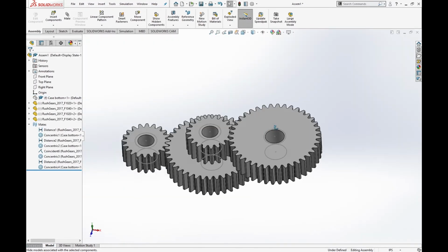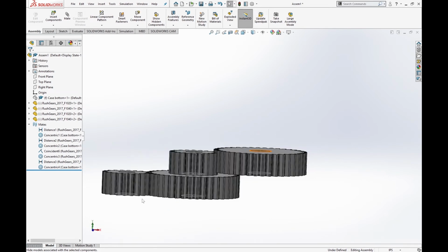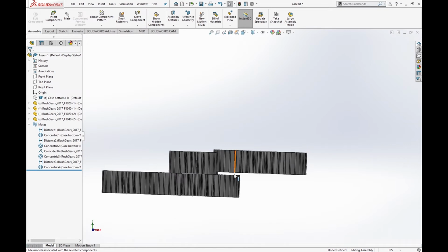and so as you can see, this has an eighth between the bottom of the case. You can't see the case right now, but we left an eighth between this one. There's a lot of space between this one, right? We have at least this gear thickness above this one, and then we have an eighth between these gears, so we won't have any issue of those.